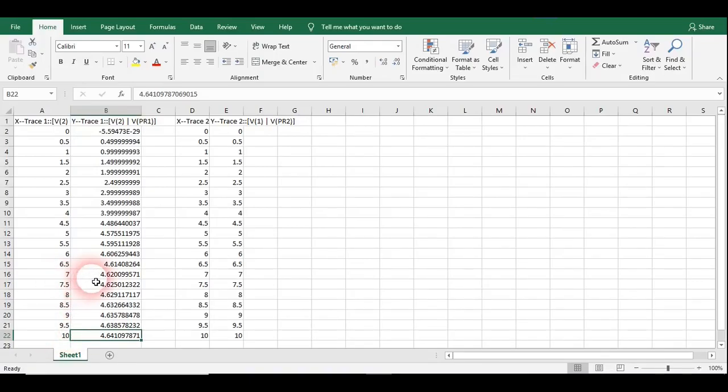So we will choose the first voltage at which our voltage across the Zener became constant. That is approx around 7 volt, or 7.5 volt. So I am going to choose here 7.5 volt. For the input voltage of 7.5 volt, my Zener has already broken down.